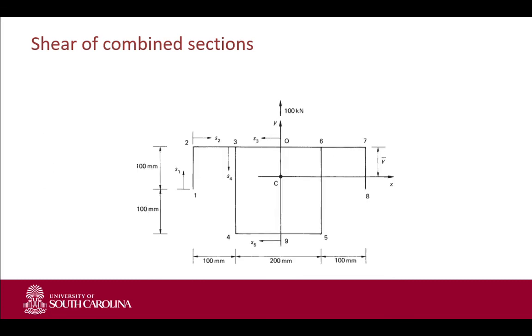So in this case, what you would do is you calculate the open shear flow section at 1. You go from 1 to 2. You calculate a shear flow at 2. You go to 3, and then you restart. You make a cut at 0. Since this is now an open section, the start point at location 0 is 0. So you calculate the shear flow from 0 to 3, and you determine what the shear flow at 0.3 is.